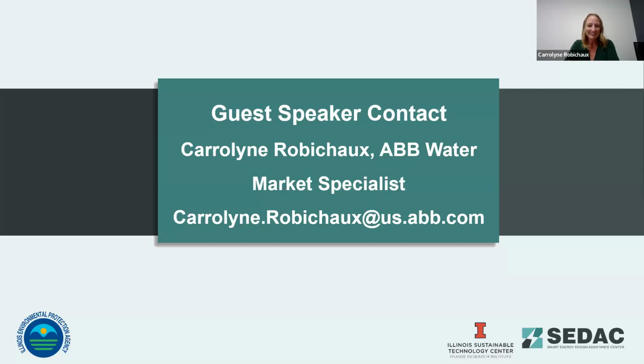I've been to a couple of plants in Illinois that have the feed forward process, and they do use it effectively. I think Wheaton is one. It's actually where the example image of the swing basins came from. So they do use that feed forward predictive model to adjust. If they've got a large ammonia load coming in, they're going to need more massive nitrifiers. So they adjust how many swing zones they have active to increase that volume of nitrifiers quickly.